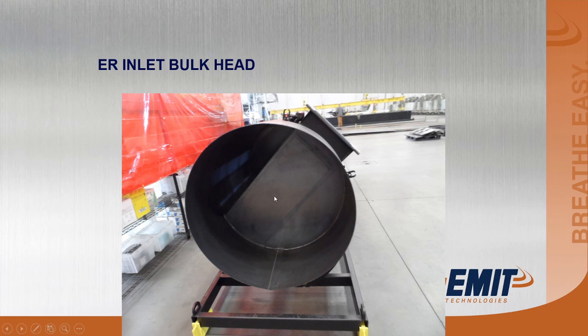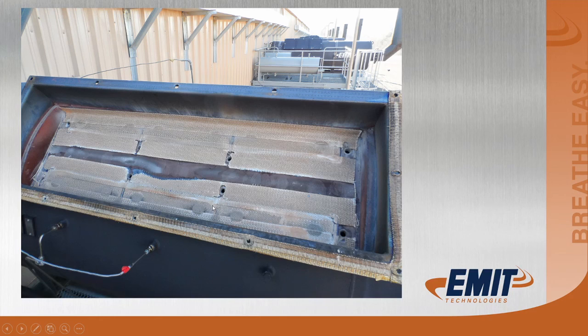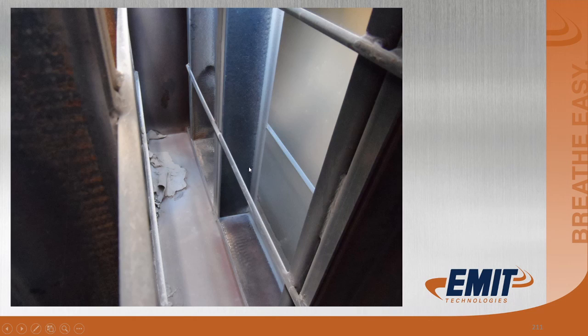Here's what the end looks like with the end cap off of the housing. You can see the exhaust gases are going to come in and go to one side, the left side, and then go through two sets of elements. Get great reduction, great performance. What the gaskets will look like as you're taking it apart. You can see this little bit of failure here, but these have been in there a couple thousand hours. These are in great shape, not an issue at all.